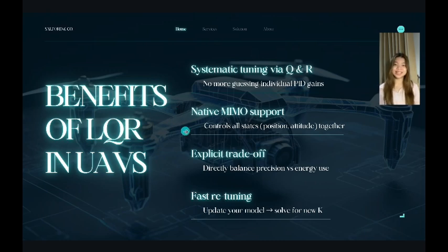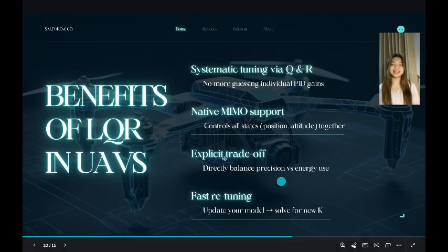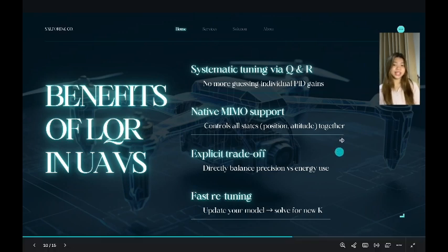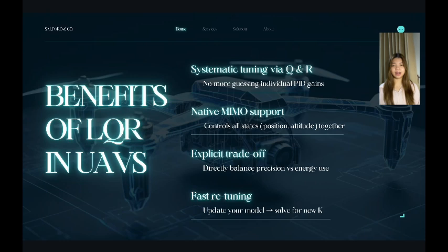The third one is explicit trade-off. We get a clear curve. So, if we want twice the speed, we'll pay in actuator effort. No mystery or unknown info. And the last but not least, which is fast retuning. If the UAV's weight or aerodynamics changes, just relinearize the model and solve again. No need for more trial runs. These features make LQR a powerful and reliable choice for modern UAV applications.